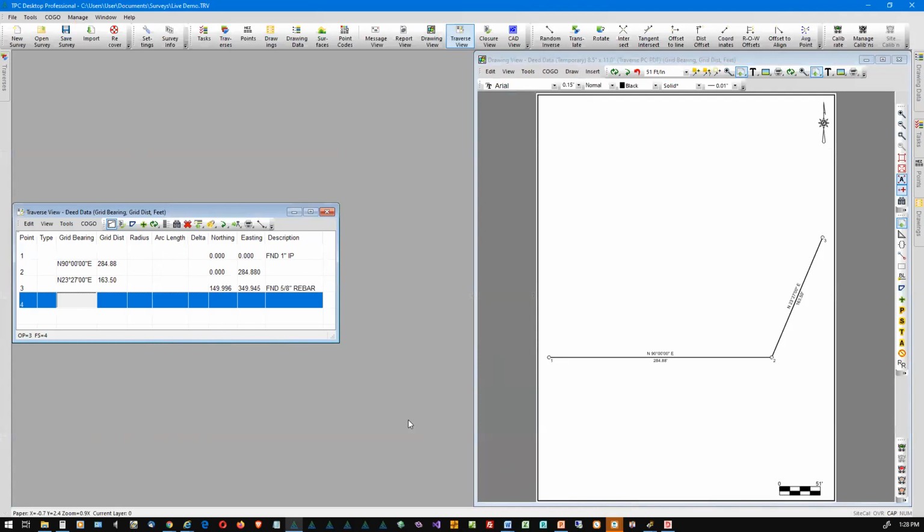Let's go this time, and you notice, now I'm going to pick up my mouse just a point. Notice over here, we're seeing this develop as we enter the data. All right, so now I'm going to go due west, so that's either 3 or 4, 90. 390, due west, and it's 291.03. All right, enter, taking me to radius and arc length.